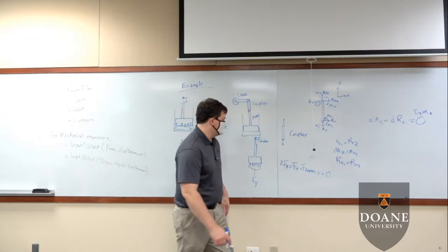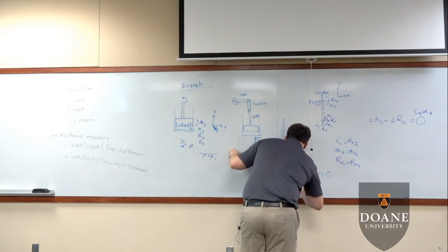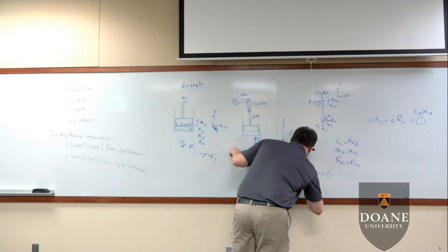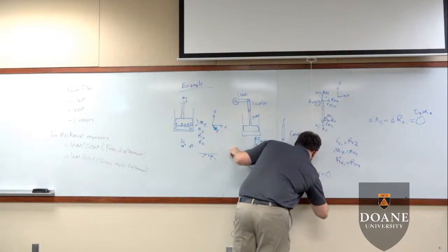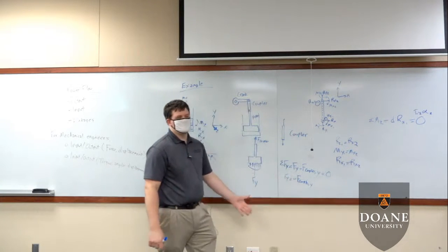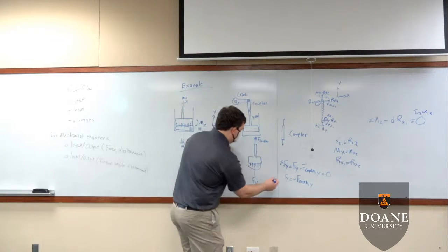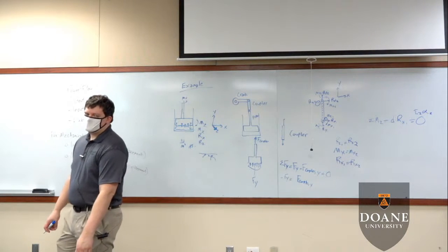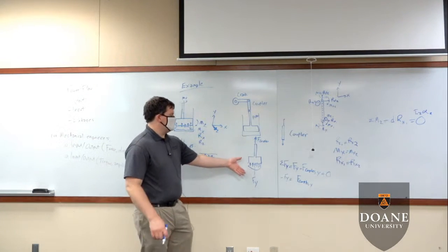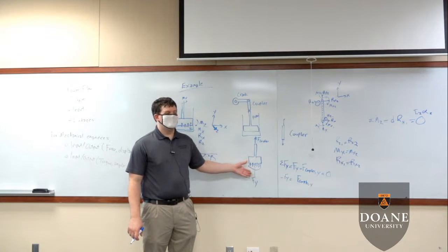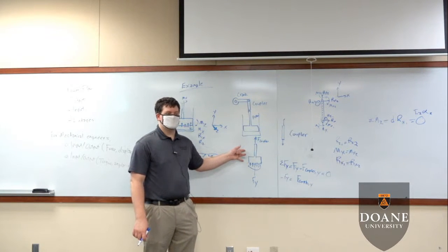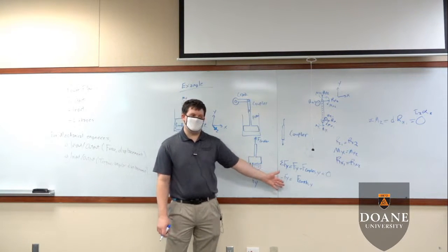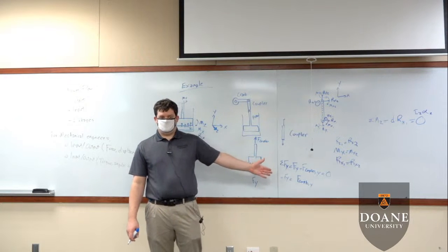This is true, which means that your Fy, well, I drew this F coupler direction wrong, so it's just going to be a negative. Your F coupler y is equal to the negative of Fy. I guess I should switch that around. The input force that's being brought into the system is being transferred through the piston head into the coupler. And we can figure that out using Newton's law.